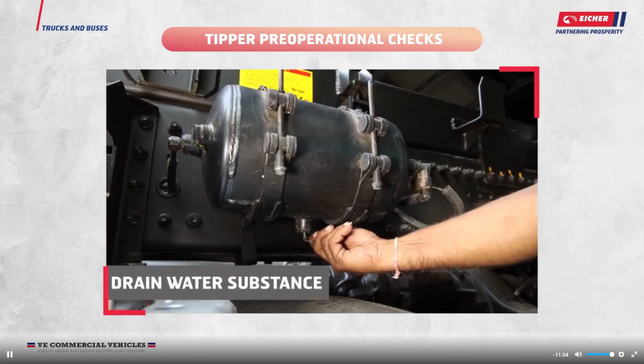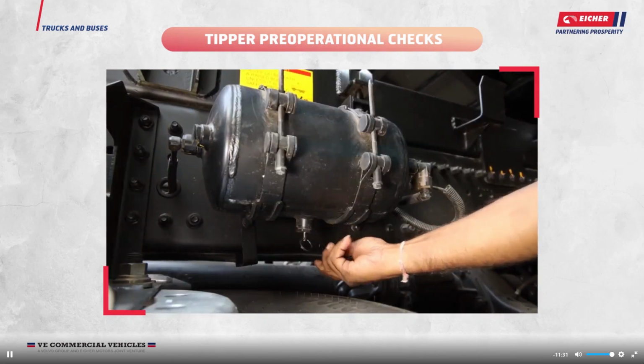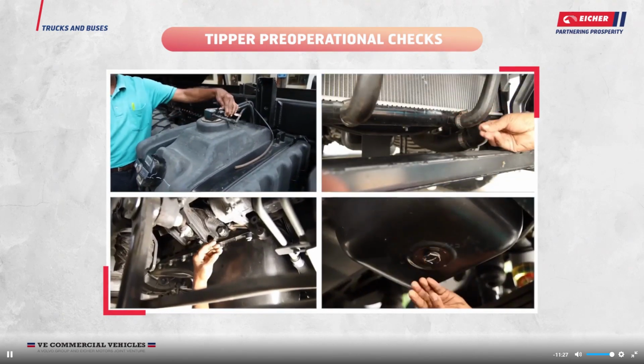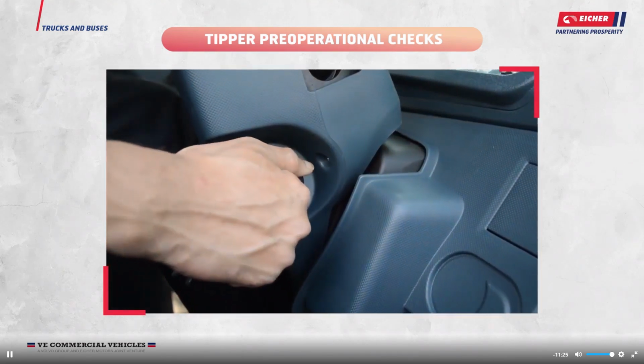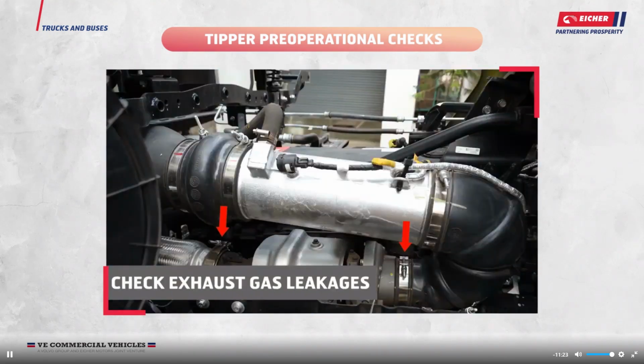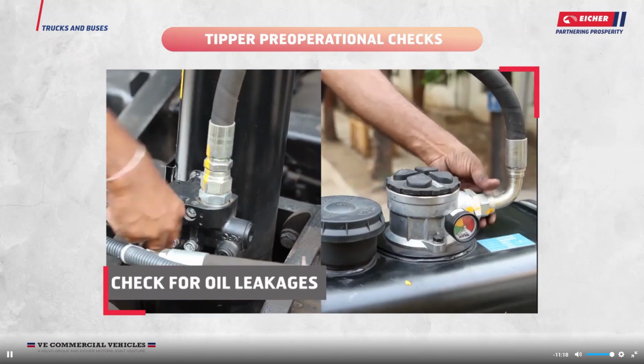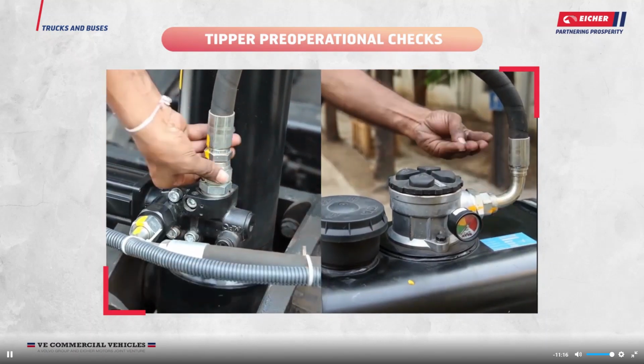Drain water substance from the air tank by pulling the drain ring. Check fuel, coolant and oil leakages underneath the vehicle. Start the engine and check for any leakages from exhaust system. Check tipping system hydraulic lines for oil leakages.